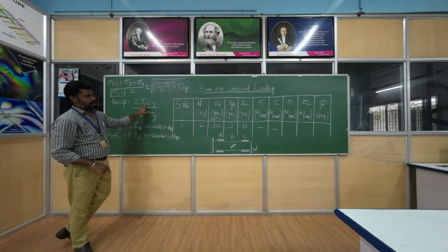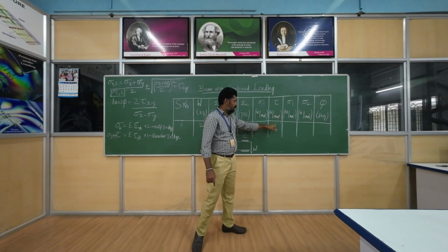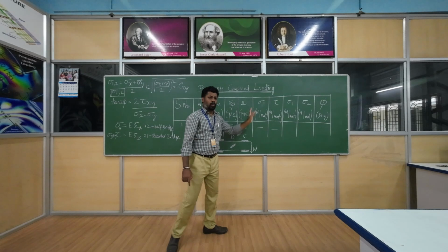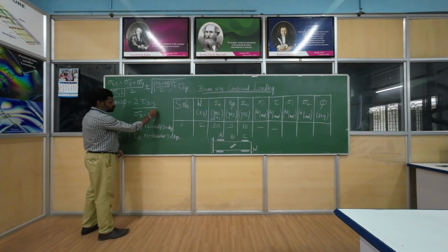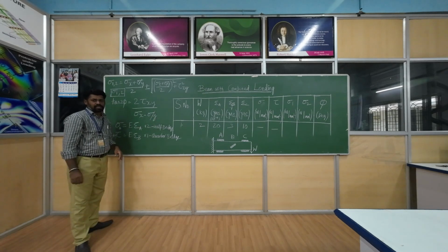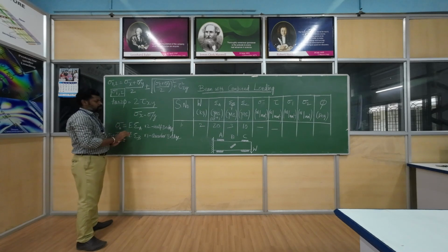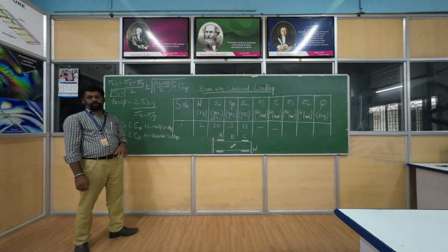So tau is known to us. We can get it from this column, and sigma we can get from this column. So we know both normal stress and shear stress. Again, sigma y is not there, there is not any vertical stress. There is no stress acting in the y direction, so you can ignore it. So just plug in the tau and sigma x, and you will get the angle of the principal plane.